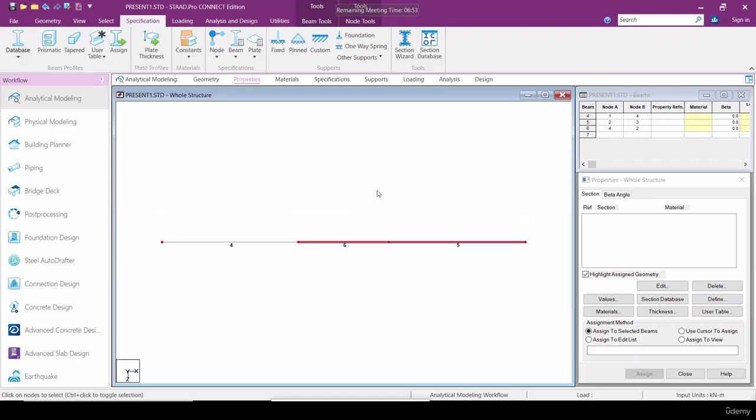Okay, because where there is no bending moment, your section can be less, right? Where there is much bending moment, your section should be high. Generally, PEB structures will follow bending moment only. That's why in all the PEB structures, you can see most of the PEB structures, not the small structures. You can observe in larger structures, they'll get tapered, okay, according to the bending moment. So you have to assign the parameter to particular beams. So this is how this tab will work.